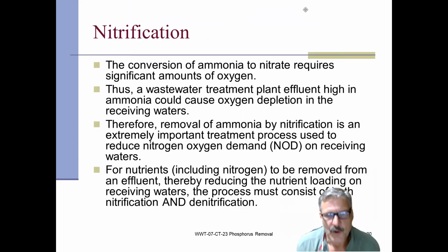So the conversion of ammonia to nitrate requires significant amounts of oxygen. Keep that in mind. And the conversion actually goes ammonia to nitrite to nitrate. Okay. It requires a lot of DO, lots of energy, lots of horsepower. Okay.